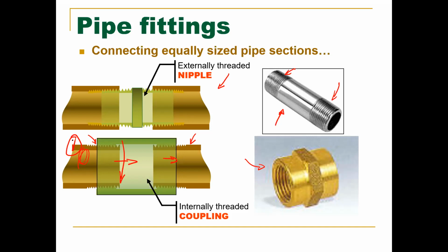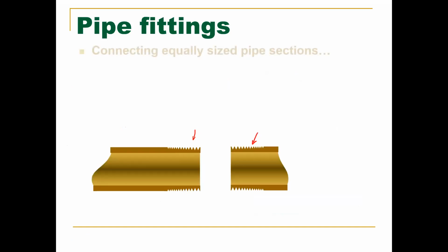right? If this was welded to a wall over here, welded to a bulkhead, what would happen? It's going to unscrew from one and screw onto the other. It's going to unscrew from one and it will screw on to number 2. So that's where unions come in.